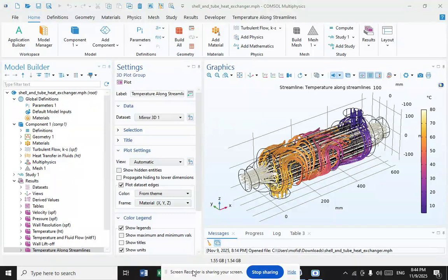Zigzag metal strips are sandwiched between flat rectangular tubes, often being soldered or brazed together for good thermal and mechanical strength. This is common in low pressure heat exchangers such as water cooling radiators. Regular flat tubes will expand and deform if exposed to high pressure, but flat microchannel tubes allow this construction to be used for high pressures.